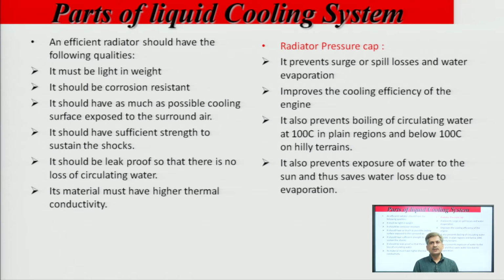It should have sufficient strength to sustain the shocks, because when the automotive vehicle moves, it will have shocks during its travel. So it should be able to sustain these shocks. It should be leak proof, so there is no loss of circulating water. Its material must have higher thermal conductivity. The higher the thermal conductivity, the higher will be the value of h and the heat transfer rate.